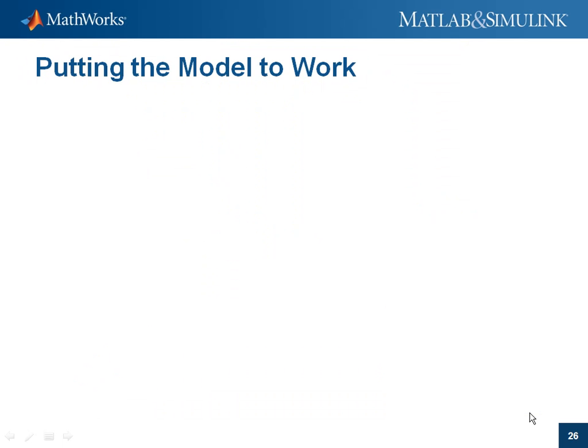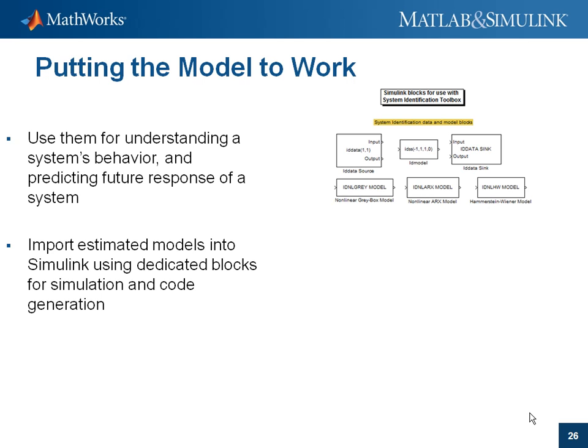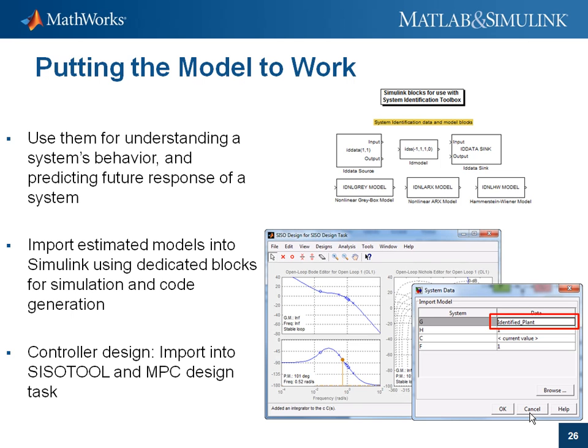When we have obtained a final model, it is a matter of putting it to work. Typical tasks are to analyze system properties and to simulate and predict responses of a system. The Identification Toolbox comes with dedicated Simulink blocks that can be directly used for Simulink simulations of the estimated models. You can also directly import the estimated models into the SISO Tool and the MPC design task for controller design.